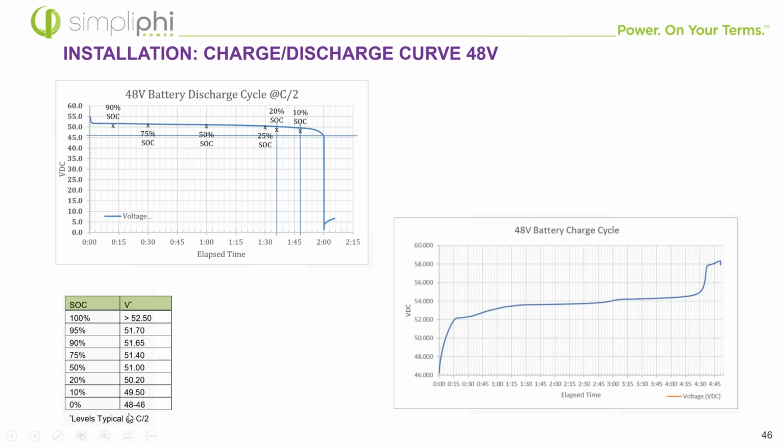The tricky one, oftentimes coming out of lead acid, if you're used to doing those lead acid installs, is that 48.0 is the absolute lowest the battery is going to go. Anything beyond that is far too low for that battery to operate in. And if we do that too many times, we can often cause damage to some of the components within the battery. So we always want low battery cutout minimum to be 48.0.